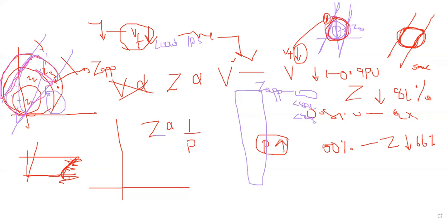If it is a fault, there will be voltage changes. If it is a power swing also, there will be voltage changes. Yes, obviously. In the power swings, voltage changes will be there, but there is no too low voltage as we can see in the fault, right? Voltage change will be there, but not too much. Like there is a stability we are already maintaining, some 10% or 5%. But if you see in the fault, the voltage will collapse like 50% or 70%, 60%.